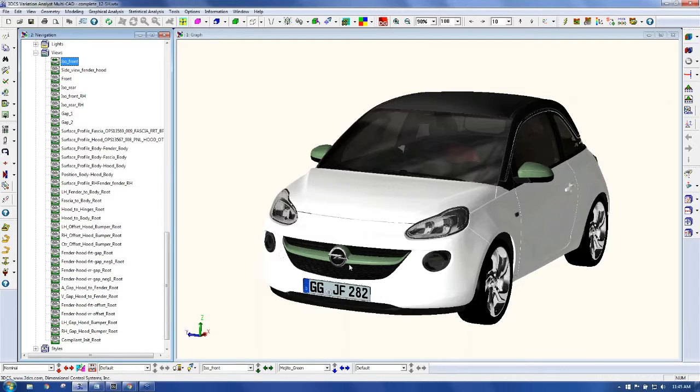Some of the ways around kind of organizing your file would be to go into your tree, grouping all of your, let's say, outside body panels that will share the same color, group them together, then add your material to that group top node, and that way it'll paint all your panels the exact same color instead of going in individually and painting each part an individual color.